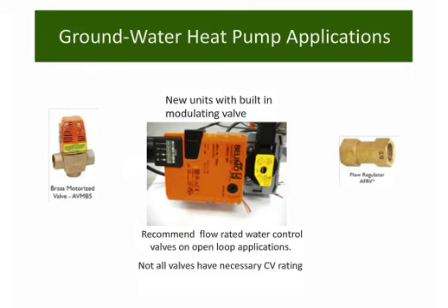A lot of what we're doing now is we're putting in an internal modulating valve with our communicating product, so we're varying the flow based upon a temperature difference. Those are very nice valves. We'll talk about them here in a moment. Flow regulators are oftentimes used. You've got to be a little careful. Sometimes those can be a little bit noisy.